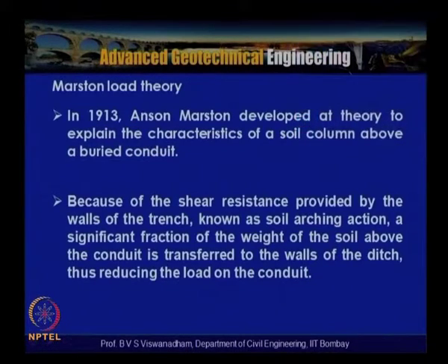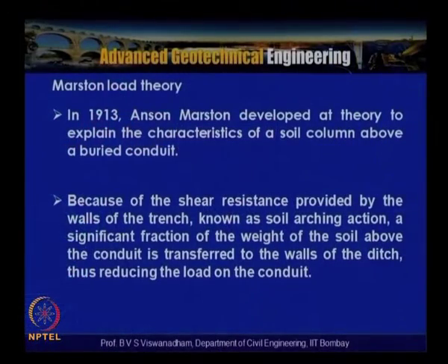So we have seen different types of conduit installations, and accordingly Marston proposed a load theory in 1913. In 1913 Anson Marston developed a theory to explain the characteristics of soil columns above a buried conduit, based on the shear resistance provided by the walls of the trench, known as soil arching. So we need to understand what this soil arching is.